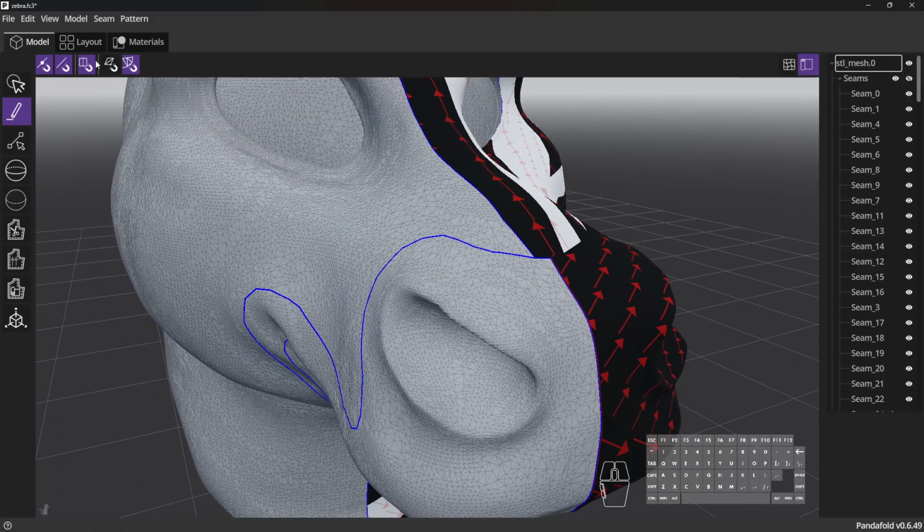Along the top here are any options or controls that are shown for the tools. So this will change as you click on tools. If I click on the select tool, it doesn't really have any options or controls for it, so it disappears. But if I click on the create seam on plane tool, you'll get specific controls here. Or if I click on the create seam on edge tool, I get a slider here. And if you mouse over it, it will tell you the tooltip again. So this is important to know because, instead of cluttering the UI with a lot of additional text, I try to use the tooltips to help describe what a particular control does.